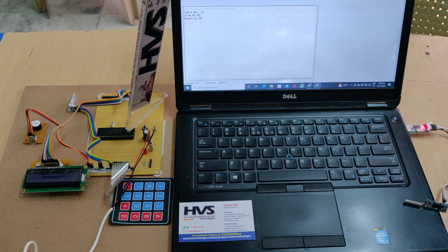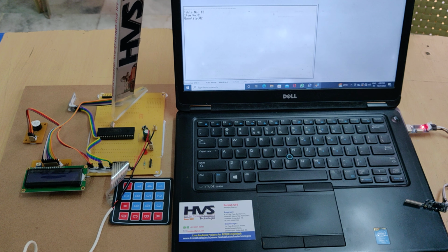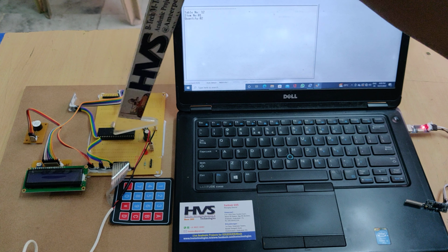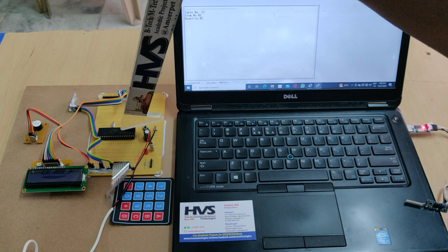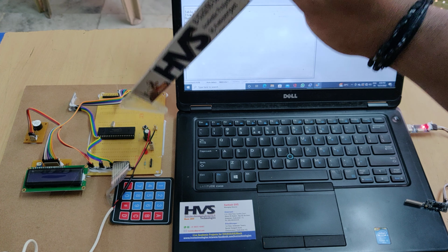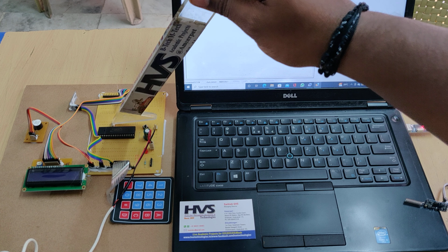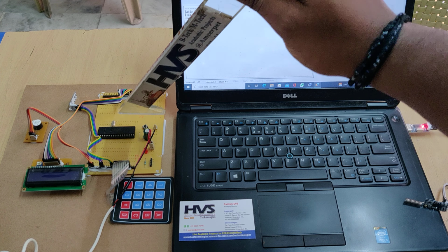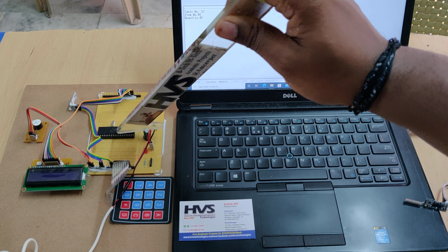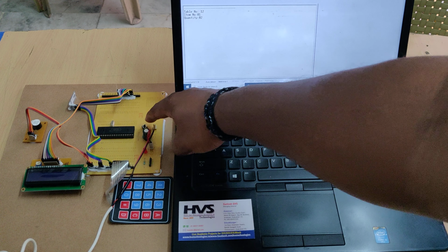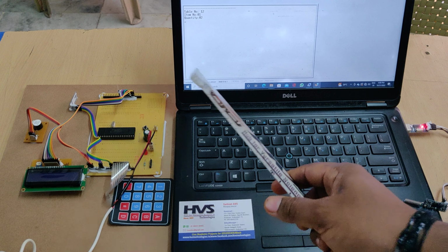On this motherboard there are three major components. One is the microcontroller, which takes care of inputs and outputs. Another is the steel-plated one, a crystal oscillator, whose purpose is to provide clock pulses to the microcontroller. We provided the set of instructions in embedded C language, and each instruction line is executed based on the clock frequency. Per instruction, the controller needs one clock pulse. We are providing 20 mega clock pulses per second, so the controller can execute 20 mega instructions per second. The third component is the reset switch to restart the microcontroller. Press and release, and the system will restart.